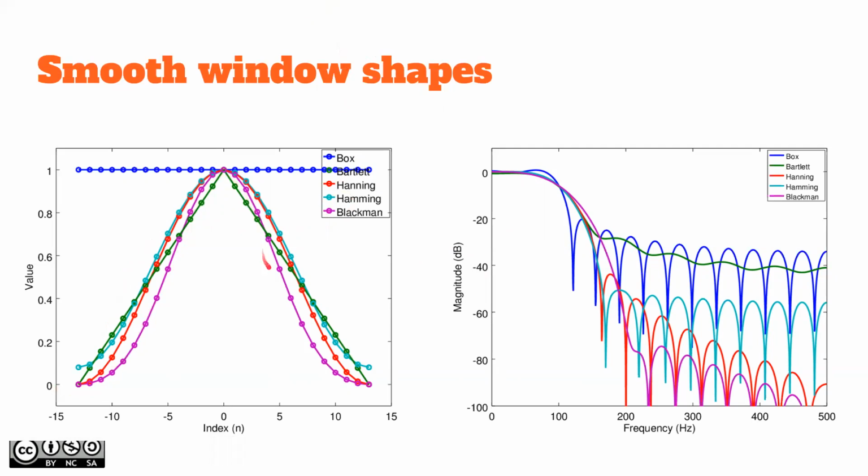On the other hand, it also reduces a lot of data points there. But here you go, Bartlett, Hamming, Blackman, the attenuation goes down and down and down. Hamming is nice, actually, since it's almost flat on the stop band. Okay, but anyways,